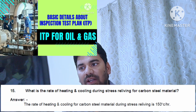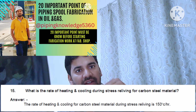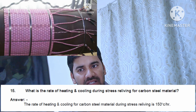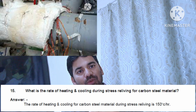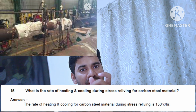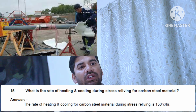Now, what is the rate of heating and cooling during stress relieving of carbon steel material? The rate of heating and cooling of carbon steel during stress relieving is 150 degrees C per hour. That means the temperature rises 150 degrees C in 1 hour, and it also goes down 150 degrees C per hour. According to this, 620 is your temperature, and you stay there for 1 hour. When you reach 620, you stay 1 hour. After that, cool down again.